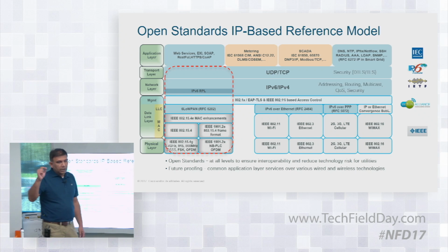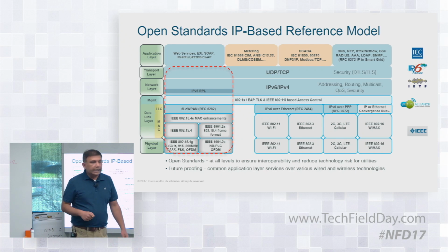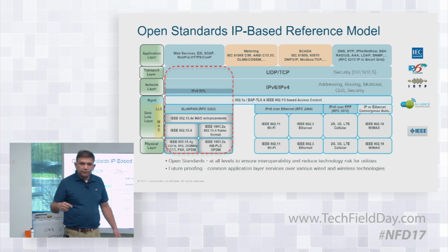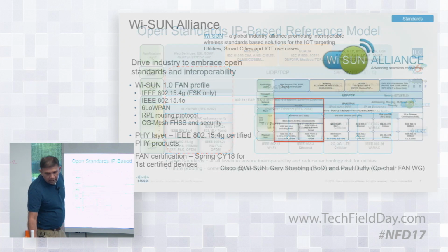If you want to do some administrative action on the device, that's a CoAP command. Talking about security, I might as well mention that we use an additional security layer beyond CoAP at the application level, message signing of management messages, because you don't want some hacker to turn off the power supply at your home.